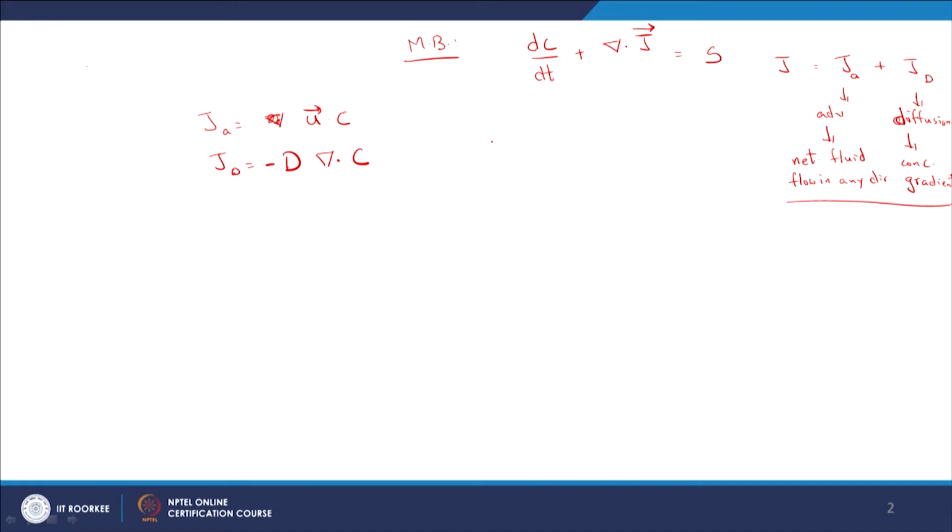So substituting the relevant terms, here it's going to be negative. Why is that? The diffusion is such that it always tries to minimize the gradient in concentration. So if the concentration is higher here and lower here, the compound would move from point A to point B. Again, random motion. So it's going to move in these directions, right? Random motion, so that after a certain time you are going to have concentration at the same levels throughout.